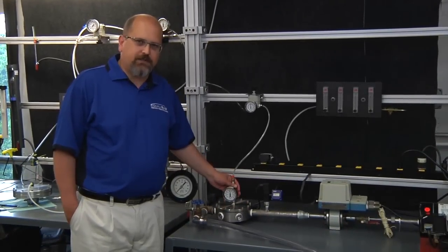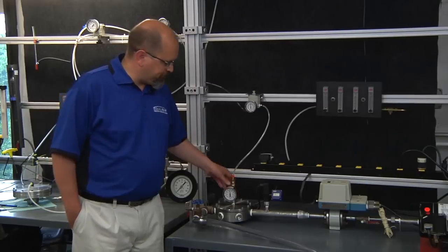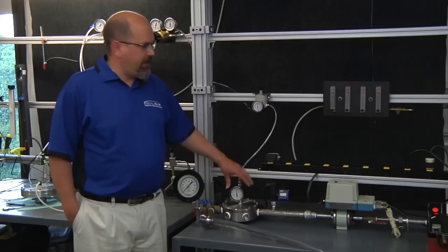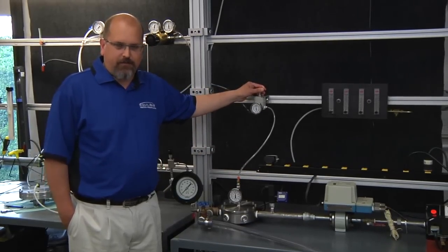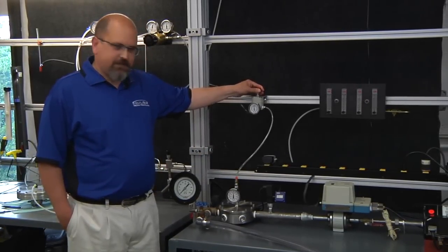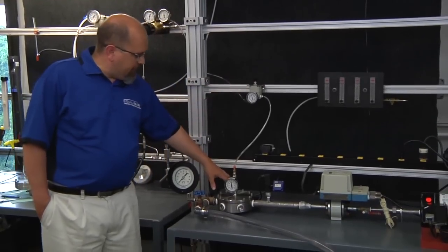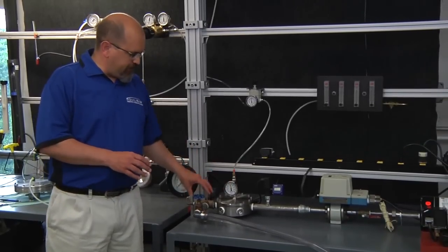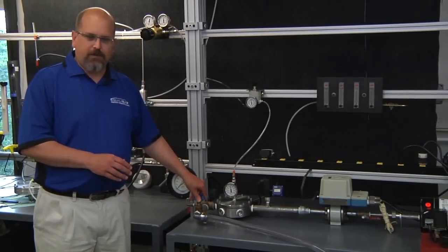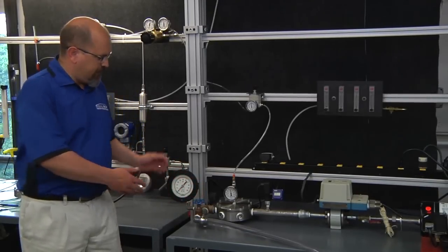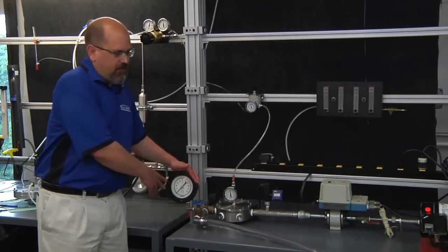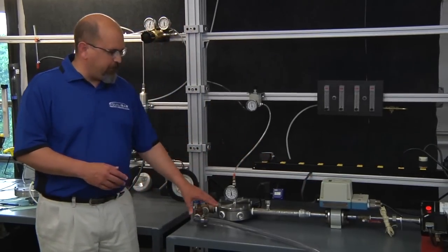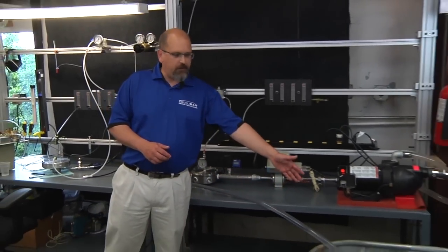This is what's going to be actually controlling the flow out of the pump. The Equilibar is a 1-to-1 air pilot operated back pressure regulator, and so I'm going to be commanding or setting the pilot pressure to the Equilibar right here with this air pilot regulator. Coming out of the Equilibar, the flow goes into the system. The system here is represented by this gate valve. I'm going to be modulating this gate valve throughout the test to show that the system pressure can vary, all while the flow rate coming through the system remains unchanged. And after the fluid is done in the system, the fluid is returned to our reservoir.